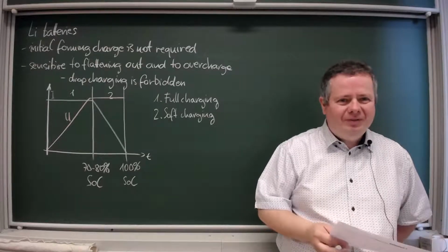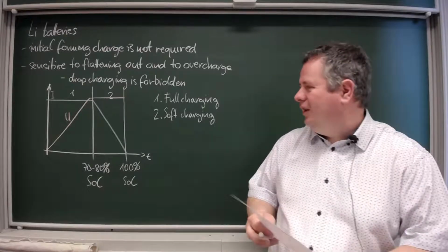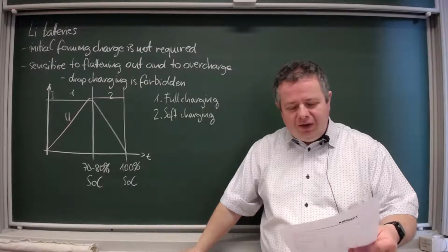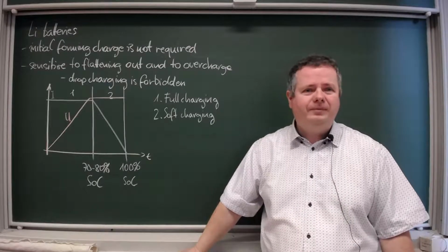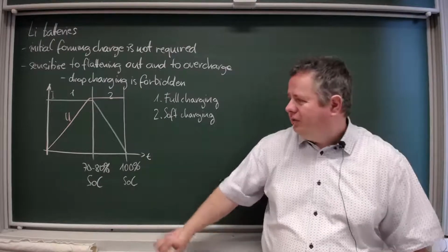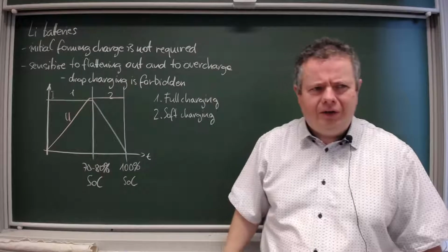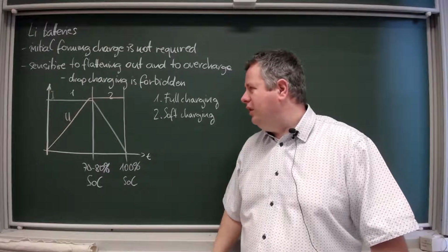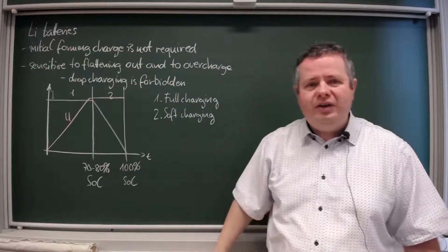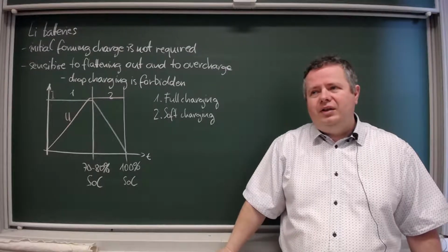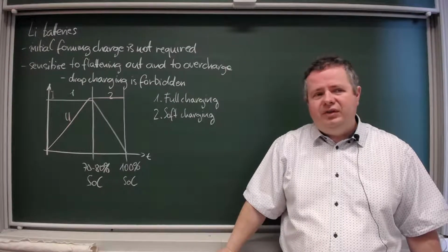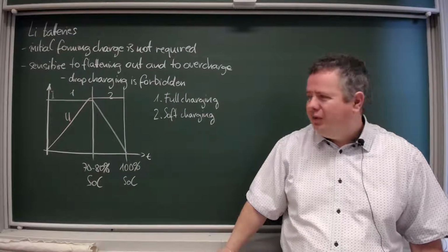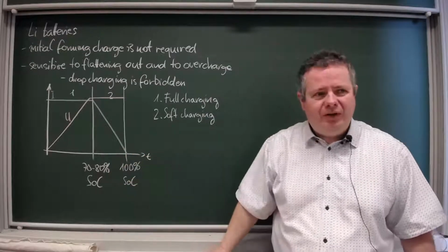Okay, this is how you can imagine the first and the second stage. This is usually how the electric vehicles are charged. You've got the fast charging here with high current, not really high current, around 100 amperes of continuous current. And once it's done, you get the remaining time as very small current. Let's say from 100 or 150 amperes, it goes down to 10 amperes. Very smooth for a much longer period. Okay?